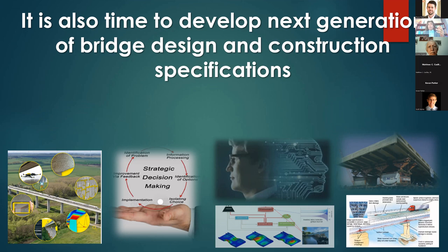There's a good friend of mine, Habib Dagher, who developed a so-called bridge in a backpack. That's an arch with FRP. So they had to develop a guide for such a design. Or let's say, for example, we had the folded plate steel bridge system. So now you have to prove that everything is according to the AASHTO LRFD bridge design specification.